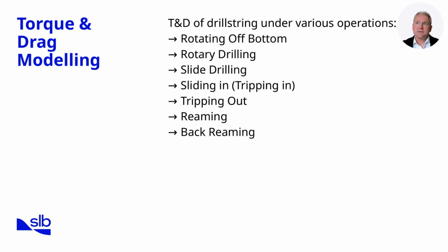Finally, during reaming and back reaming, the torque and drag responses highlight wellbore condition, rugosity, and cuttings beds. Together, these scenarios demonstrate how torque and drag modeling provides the framework to predict where problems may arise and to design strategies that mitigate risks. Next, we'll see how this modeling supports design decisions.